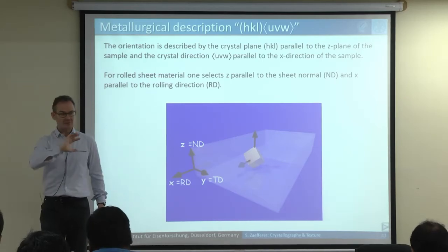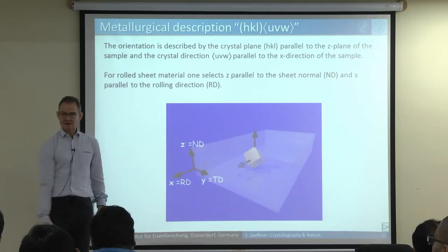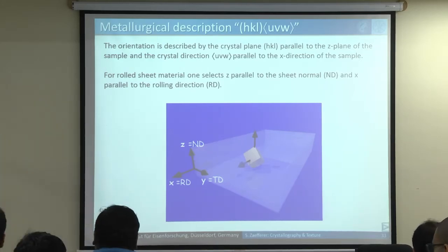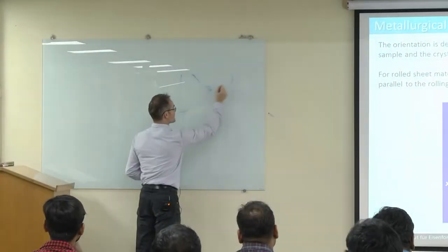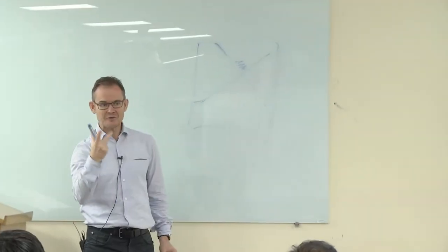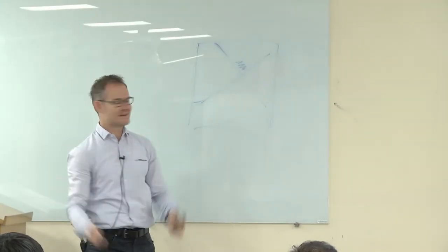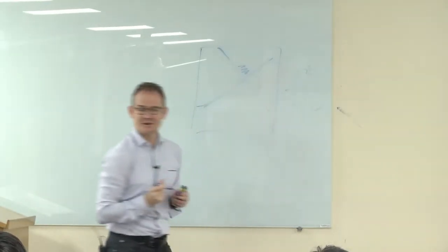And particularly when you do then correlation with grain boundaries or with dislocations in a real image, suddenly the things do not match. So you have a picture and you see a grain boundary of a twin. So you know this should be a 1, 1, 1. But in your pole figure, the 1, 1, 1 looks like that. So why is the 1, 1, 1 indicated to be perpendicular to that? What have I done wrong? And then it's often that you have mistaken right and left hand. And then the picture and your pole figure does not fit any longer together.